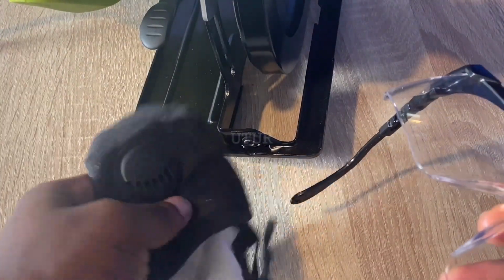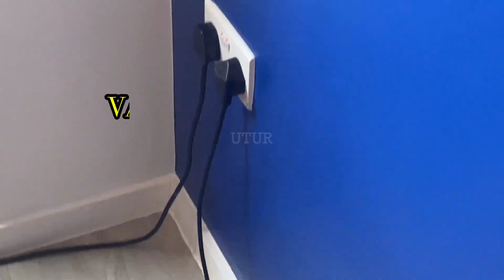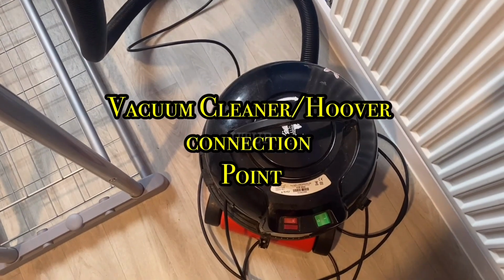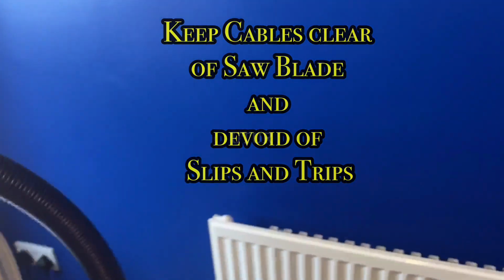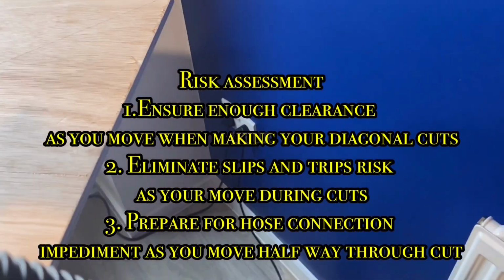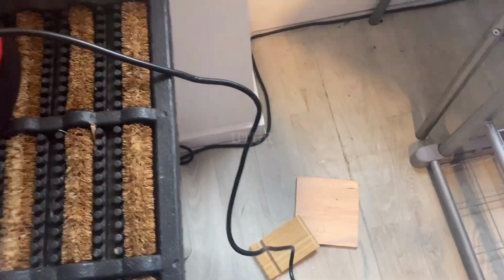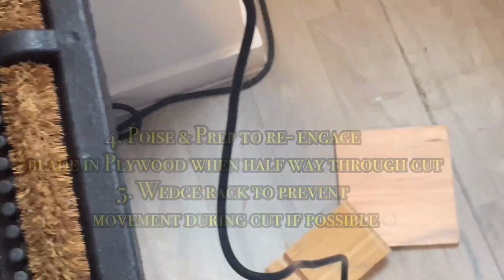The next step of the process would be to carry out a risk assessment with regards to slips and trips, where you've got one side of your vacuum connected and the other side where you've got the circular saw connected. Make sure that you've got enough clearance when you're moving. And you can also see that the vacuum hose is on the right. So halfway through the cut, I'd have to adjust so that the vacuum hose doesn't get in the way. And here you can see the working tool or the circular saw's connection point.